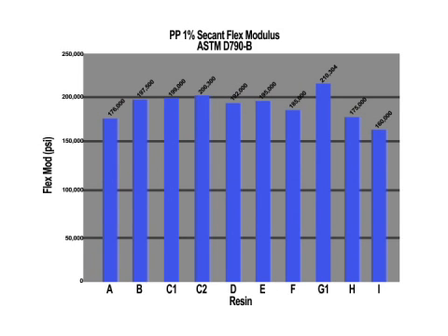In verification of the properties used in design, we look at a number of commercially available resins. Forgiving the nomenclature I use on the x-axis of this chart, what we are actually depicting here is the fact that we have tested not only virgin resins, but we have also tested virgin resin with pigment, virgin resin pigmented in pipe production, and actual samples from the pipe wall. You see the 175,000 depicted as the red line there as the short-term flexural modulus. Each of the resins that we show have exceeded that value with the exception of resin I to the far right hand of that chart.